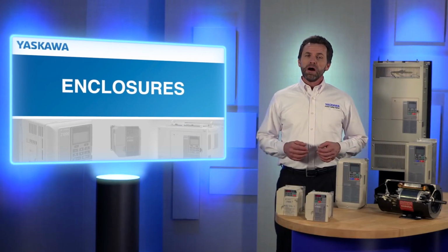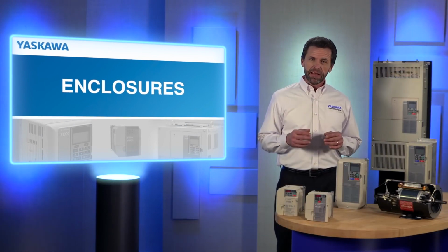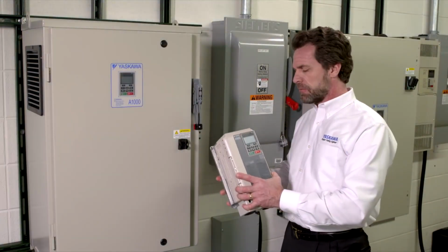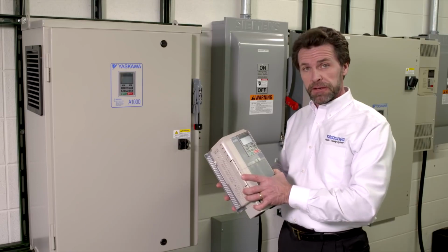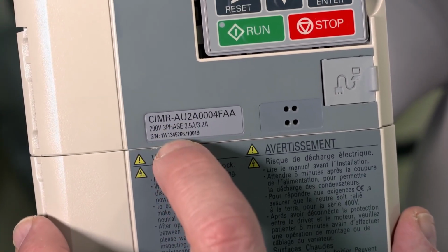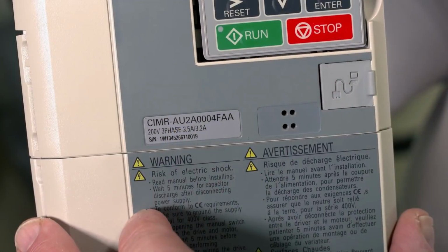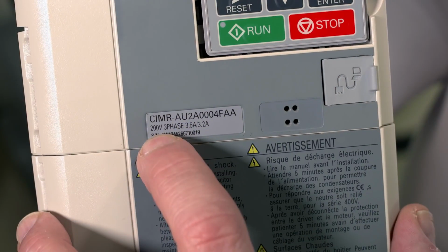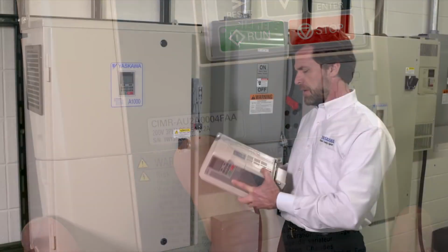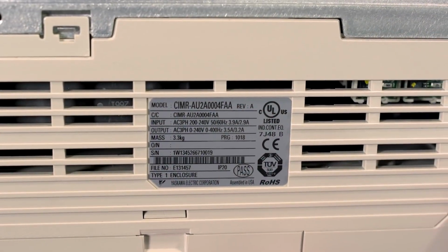Now that we've walked through the inner workings of a variable frequency drive, let's head to the lab and take a look at the outside of the box. You'll find information about each drive on its nameplate. The front cover has information such as the model number and serial number, which you would need if you ever have to contact tech support. You'll also see the voltage class and the amp rating in normal and heavy-duty situations. On the side of the drive, you will see the full nameplate with all ratings and certifications.